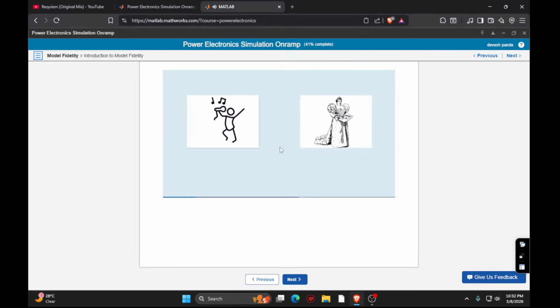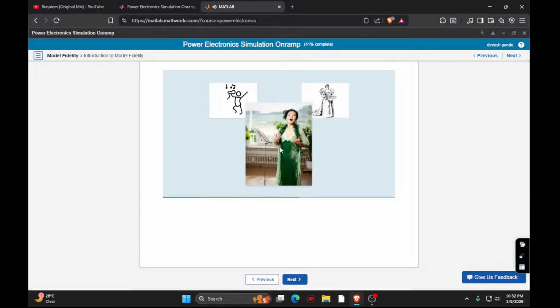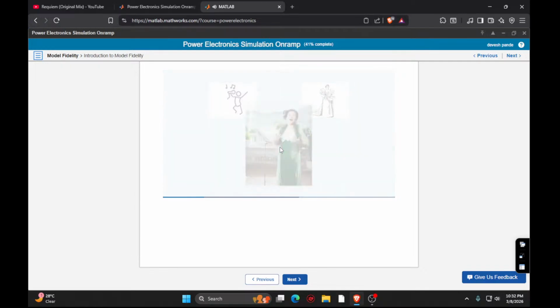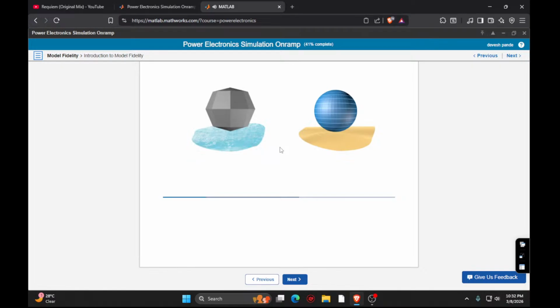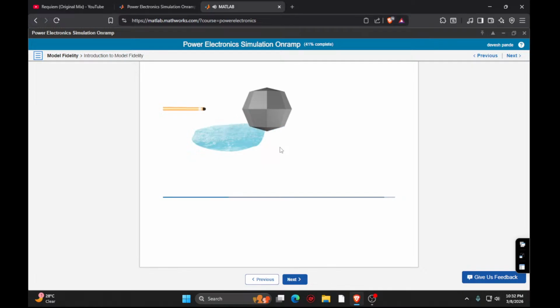Your drawing and Leo's are two examples of fidelity, how closely a model represents the real-world system. A low-fidelity model loosely represents the real-world system. It may make coarse approximations, like ignoring friction, transient behavior, or your singer's nose. Low-fidelity models typically give broad, representative characteristics of a system and simulate quickly. They can be useful, for instance, if you need to model a component's input-output behavior within a larger system.